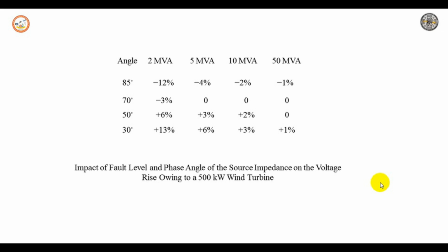So this increases the highest 10 minute voltage magnitude, where there is only a 1 volt increase in all the 3 sections for a short duration. If a 95 mm cable is used, the case would be different. Here it will produce 11.4 volts, almost 5%, which is unacceptable over voltage. This would likely be caused by using the 95 mm square cable.